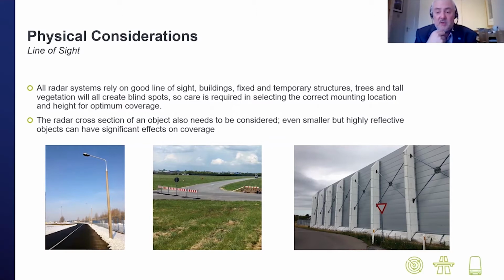The term radar cross section is basically a measure of the equivalent echoing area of a target. The RCS figure determines how much of the radar power that is transmitted onto the target is reflected back towards the radar. Radar cross-section doesn't always bear a simple relationship to the physical size of the target. Even very large targets, such as wind turbines, for instance, can have a very, very low radar cross-section because of the materials used in their construction and also the angles of that construction.